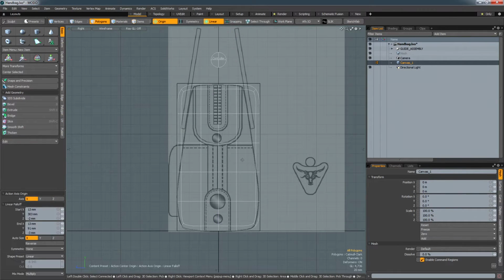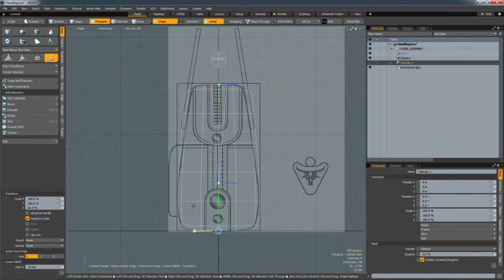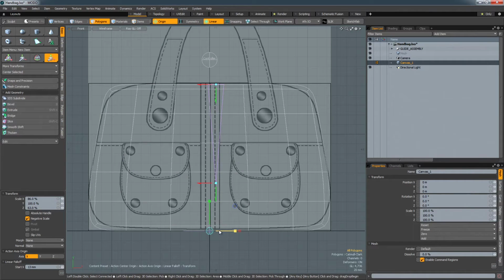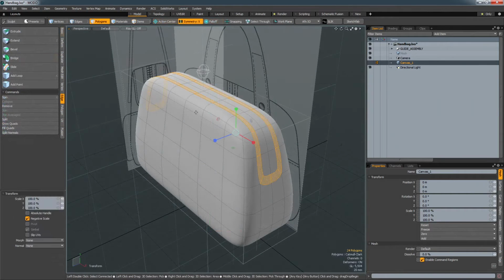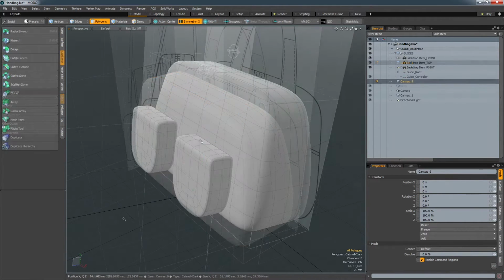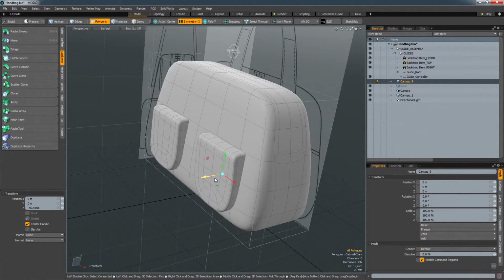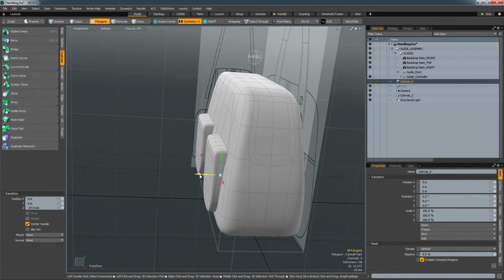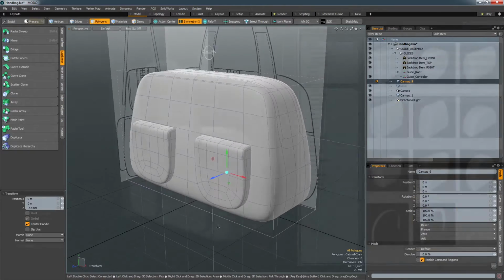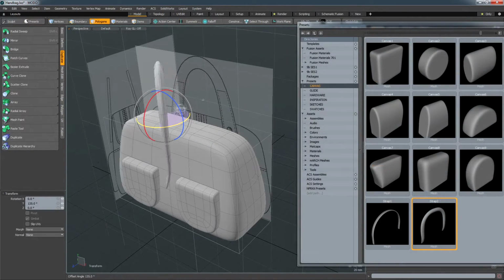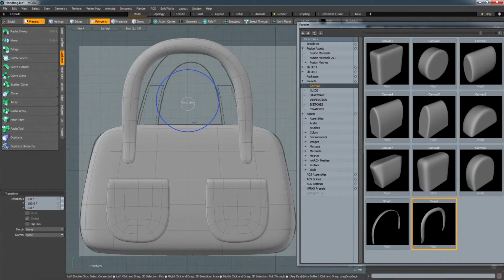One of the most powerful features that can help you in this process are fall-offs. These allow you to define an influence area and then deform the shape accordingly. Importantly, the fall-off remains live, so subtle adjustments can be made. Elements of the volume can be selected and worked on independently to build more subtlety into the design. Additional volumes can be loaded into the scene and then set into the main volume to quickly create more complex shapes. This is perfect for defining pockets or even the position and location of straps and handles.